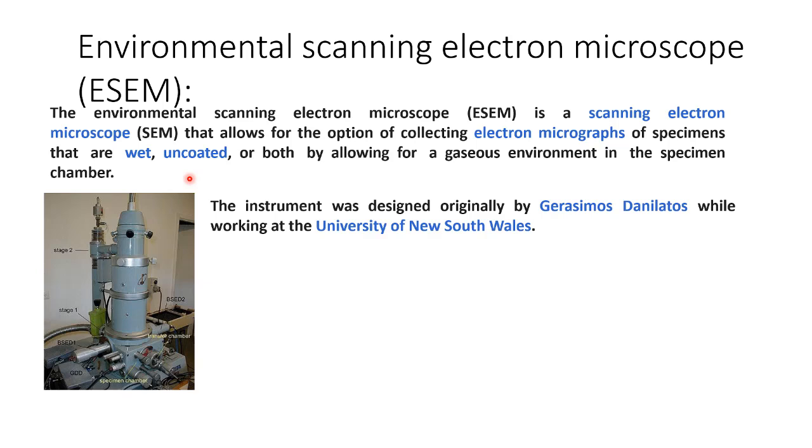This instrument was originally designed by Gerasimos Danilatos at the University of New South Wales. This is the typical ESEM setup. Here the vacuum is still present in the column, but the portion where we keep the sample does not use much vacuum. So there we can keep wet and uncoated samples.